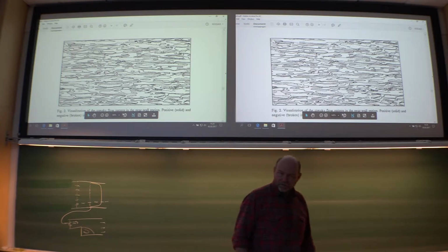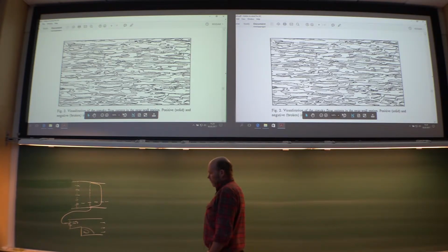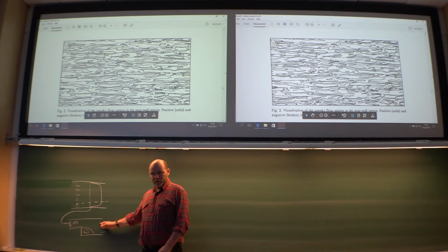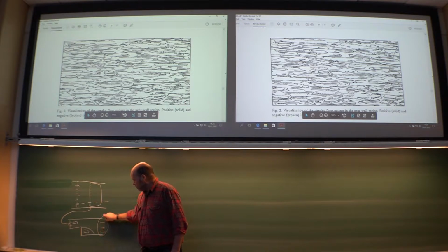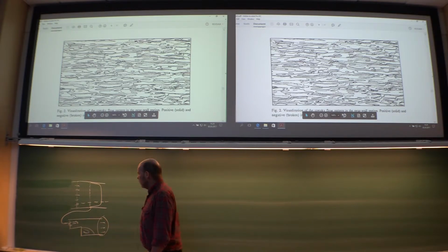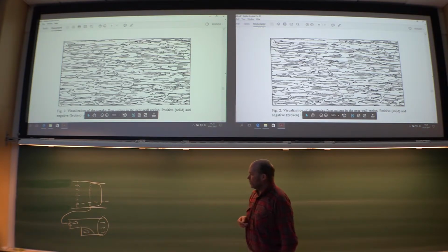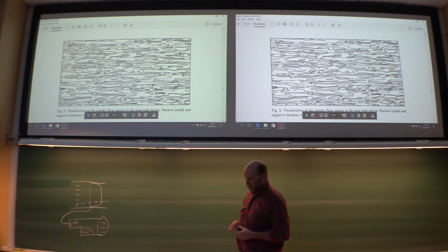That's possible. For the outlet, you have no idea. So there you typically would use some Neumann condition, derivative equal to 0. It will be an error, but hopefully that error shouldn't propagate too far upstream. So you should have decent results here in the end. So that's one way around this problem, finding input values for a fully developed turbulent flow.